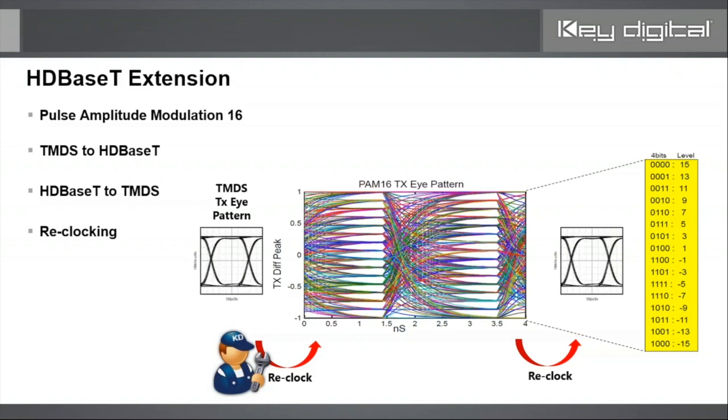Well, anyways, your competitor is saying that whenever I work with this cable box, I need to add a splitter in front of the transmitter because of a clock stretching problem, a splitter, or we would say a fixer, right? And it would have to reclock that signal on the front end in order to make it work.